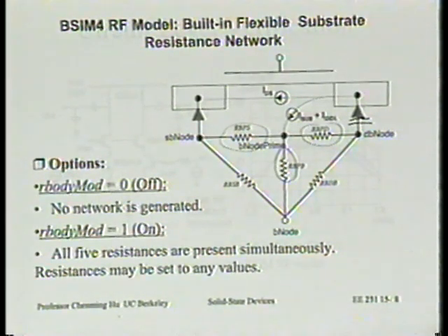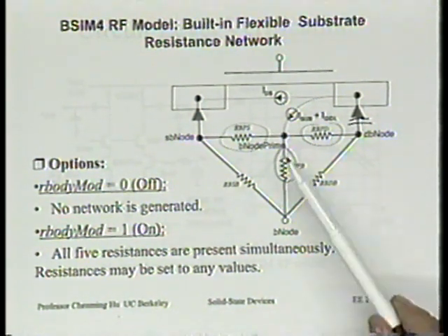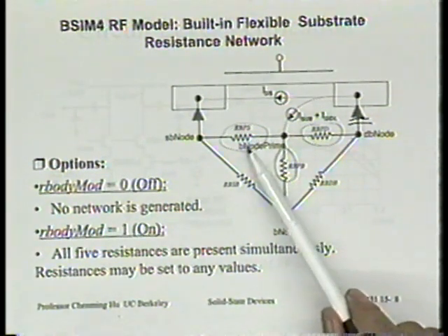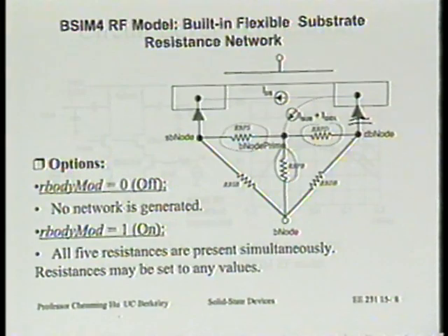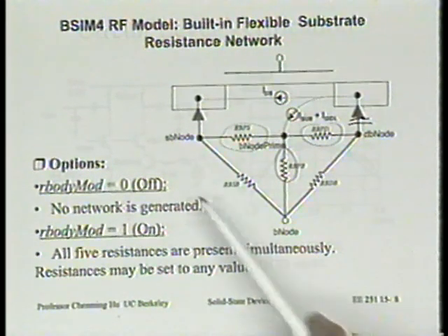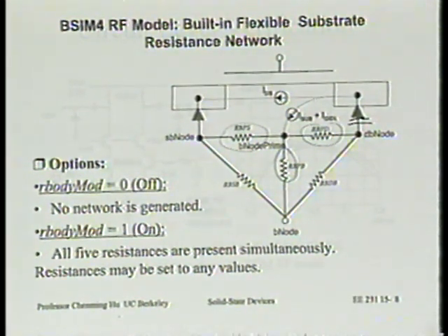There's no question about diffusion or drift or impact ionization. Simplest physics. But we actually found that's mathematically the most challenging problem. We don't know how to come up with the equation that we have confidence about giving us a value. If I just tell you the doping concentration, give you the R and W, give us a value. Right? So this is definitely an area for research. Okay? Substrate modeling.